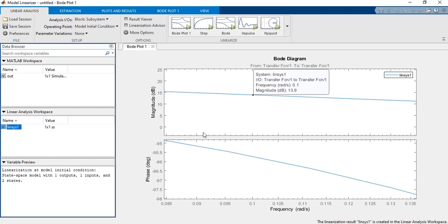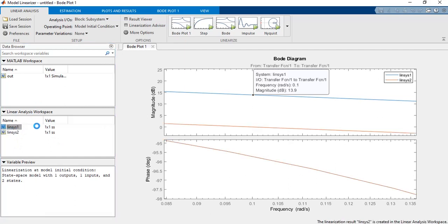So in this page, we need to press Bode plot 1, so it will generate the new Bode plot. So you can see now that the second simulation produced at frequency 0.1 radian per second is equal to 0. This is 0.1, approximately 0.1. So we got 0.00. So it is actually 0.